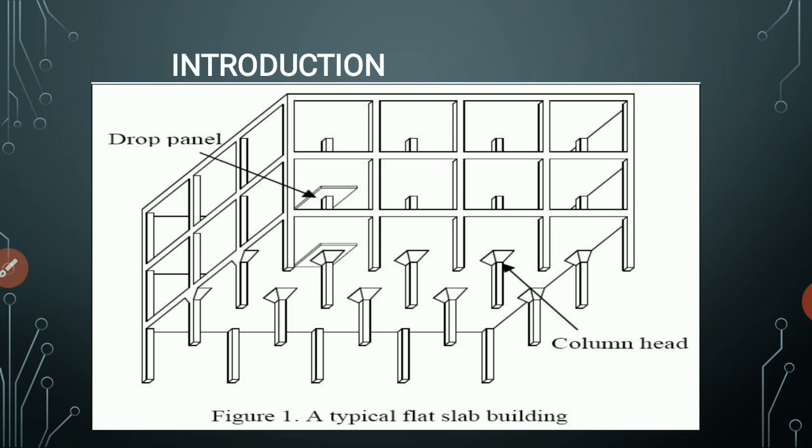Also, in some cases the section of the column at the top where it meets the floor slab or drop panel is enlarged to increase the perimeter of the critical section for shear, and hence increase the capacity of the slab for resisting two-way shear and to reduce the negative bending moment at the supports.